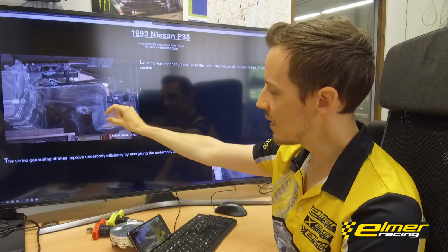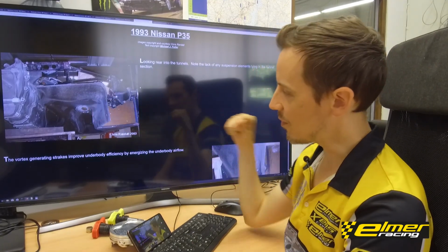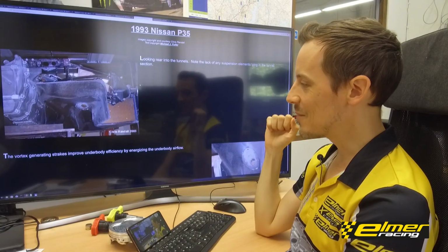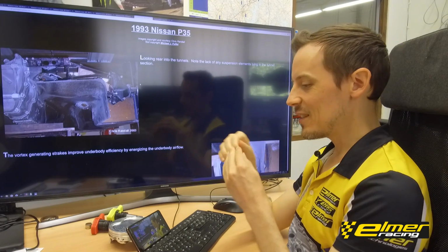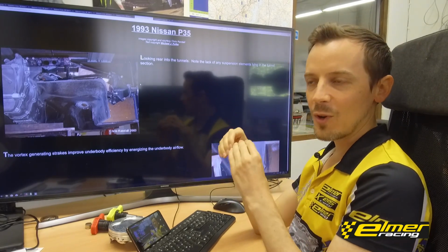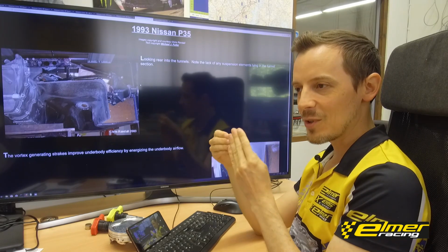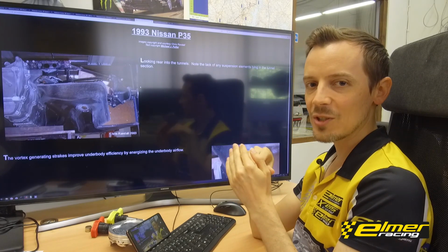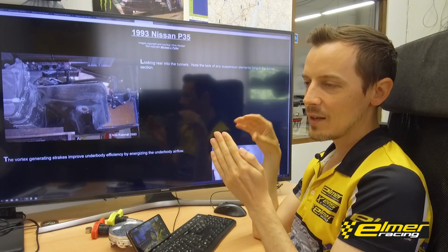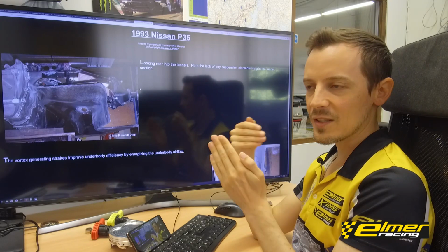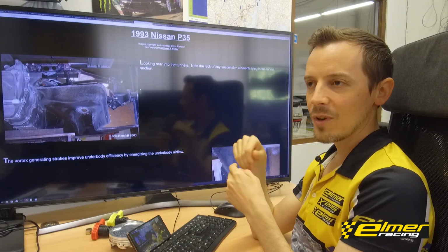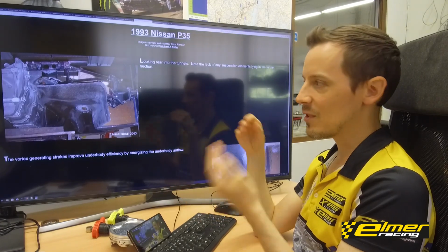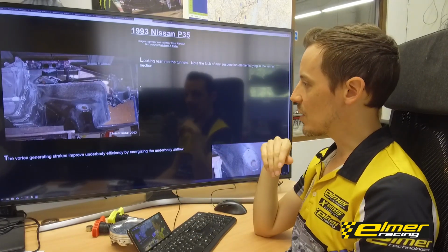And even having some small gaps for the through hole for the lower A-arm, for instance, is a really bad idea, because just the opening will already disturb the flow. Then if you don't seal that opening somehow, which you typically can't do if you have a movable suspension component going through there, the flow going through that hole, because of a pressure difference there, will upset that flow, and then you can't run the diffuser as aggressively as you otherwise could, and you end up losing lots of the potential from that.